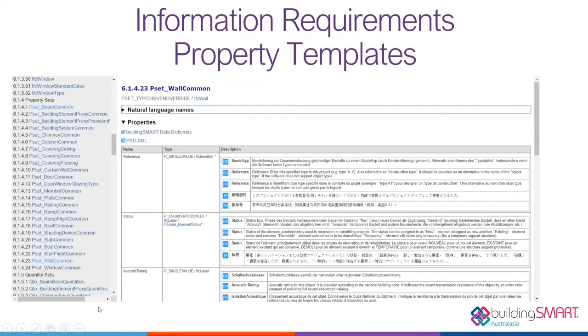Normally, when someone asks for an IFC file, they should be clear about three things that I've just touched on. First of all, the version. Do they want IFC 2x3 or IFC 4? The second thing should be the model view definition or the subset of IFC that they want this particular file to be compliant with. So that's probably going to be coordination view, or it could be something like a design transfer or bespoke design model view definition. And the third thing should probably be them telling you what are the attributes and properties that they want on the objects when you give them the IFC file.